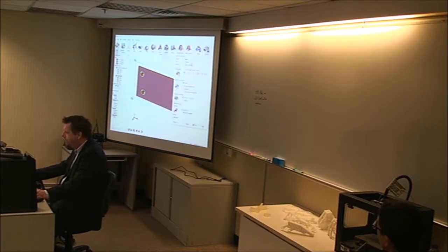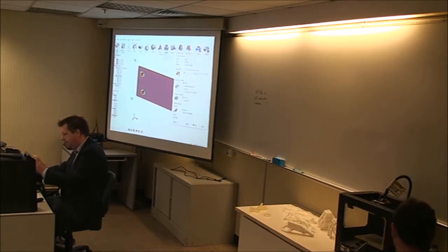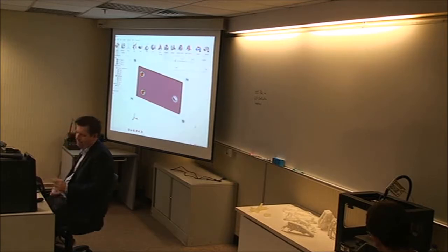So now I can run it. I'll do topology. I can minimize mass and put stress constraints with a safety factor on, or because I'm just using arbitrary loads, I'll just maximize the stiffness using 25% of material. And here's that minimum dimension size. I want nice, good chunky members to make my sketching easier. So I'll now run that.